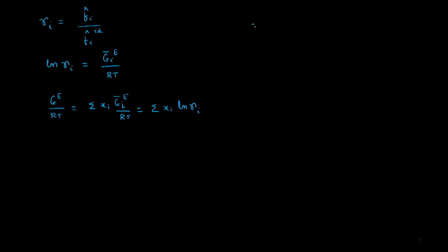And the final relation we had yesterday was for the liquid phase, the fugacity of species in the mixture is x_i gamma_i P_i sat, where P_i sat is the vapor pressure at the temperature we are interested in, times phi_i sat, that is the fugacity coefficient for the pure species at the temperature of interest, and this will be equal to the fugacity of the vapor phase, which is y_i times P, the partial pressure, multiplied by the fugacity coefficient for species i in the vapor, phi hat, right?